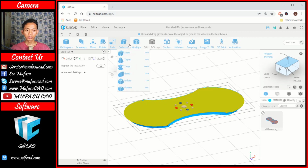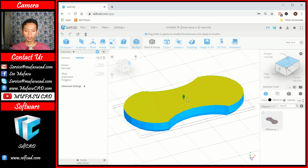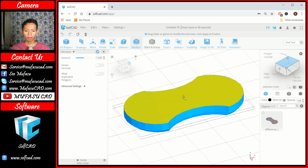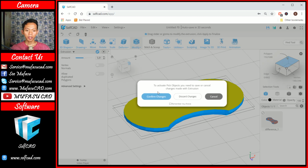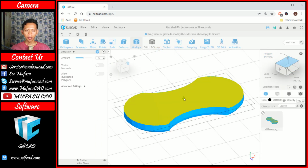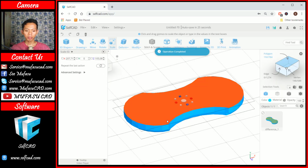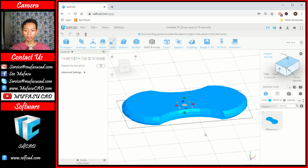You can use extrusion command to extrude these objects. Move into here. I will use extrusion again. Click confirm change, and then we can use extrusion. We can click OK, and then we can use scale command to scale the face into this point. So we already created these simple 3D models.